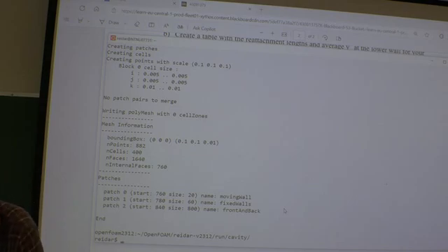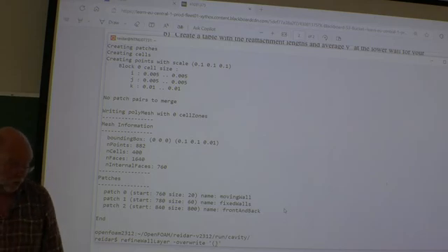Okay, let's try this refine wall layer on this mesh. I mean, the mesh was uniform here. Refine wall layer, then minus over right, and then we need the name of these walls.